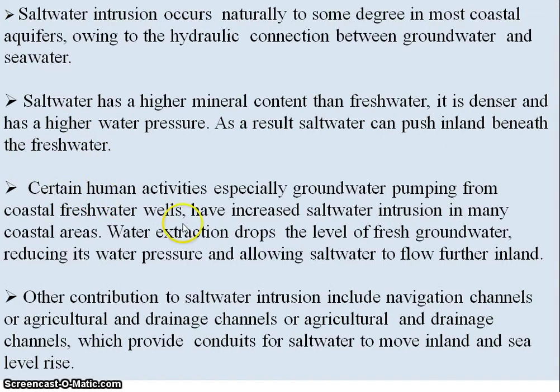Certain human activities, especially groundwater pumping from coastal freshwater wells, have increased saltwater intrusion in many coastal areas. The water extraction drops the level of the fresh groundwater and reduces its water pressure, allowing the salt water to flow further inland.